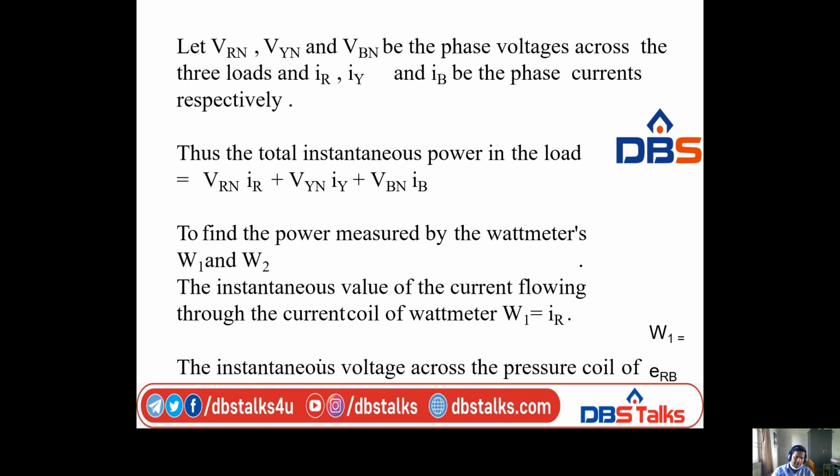Let VRN, VYN and VBN be the phase voltages across the 3 loads, and IR, IY, IB be the phase currents respectively. Thus, the total instantaneous power is VRN into IR plus VYN into IY plus VBN into IB.